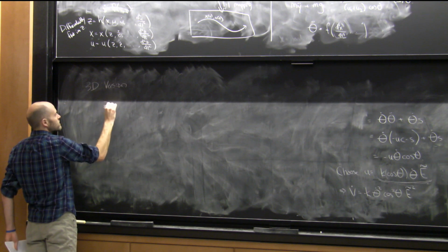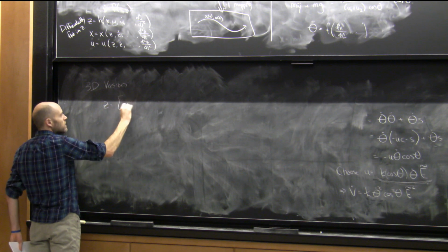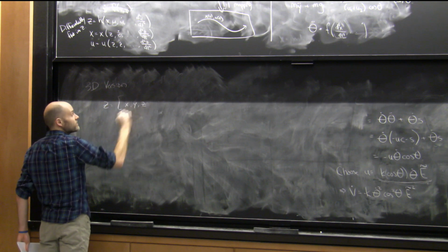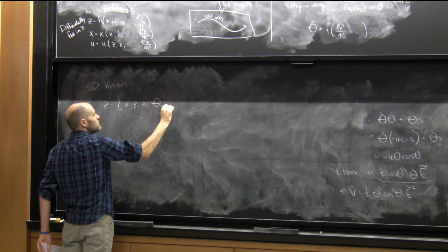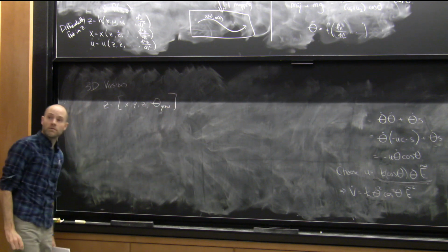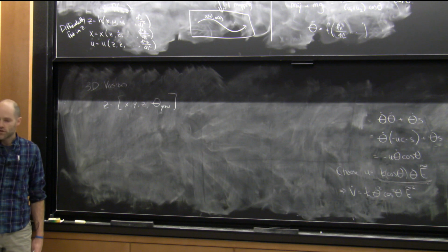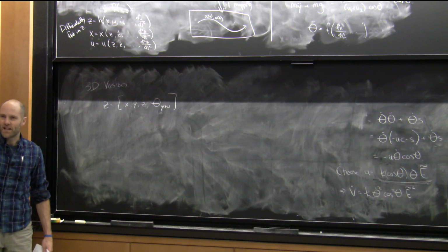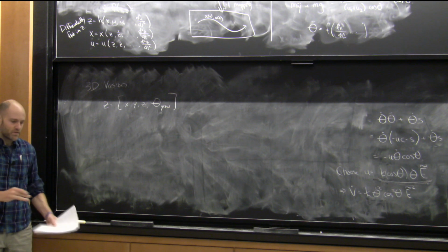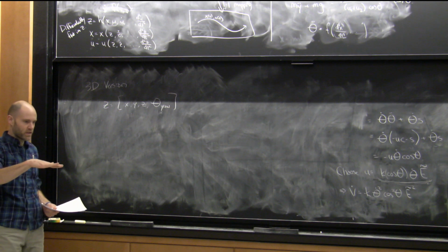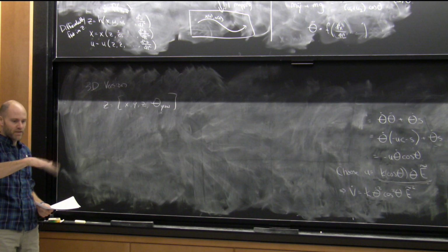The flat outputs of choice are x, y, z of the center of mass plus the yaw angle. Yaw, right? It's kind of the one you probably don't care about, right? If the quadrotor is sitting here, that's pitch, that matters a lot, right?